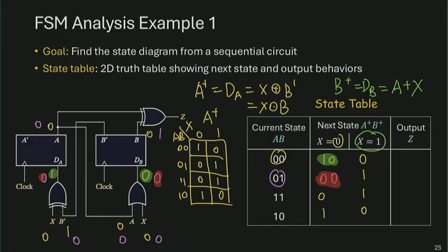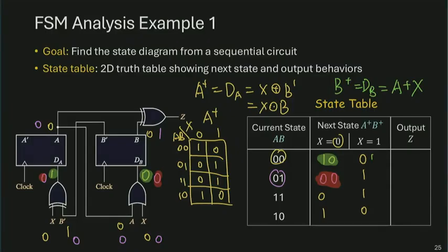So this whole column will have the next state for B being 1, a whole column of 1s. And also the bottom 2 rows when A equals 1. So really you have A equals 1 over here, X equals 1 over there. If you look at those two separate columns as a whole K-map, that's how I fill out the K-map. This is the implicant X. These 4 1s are the implicant for A.